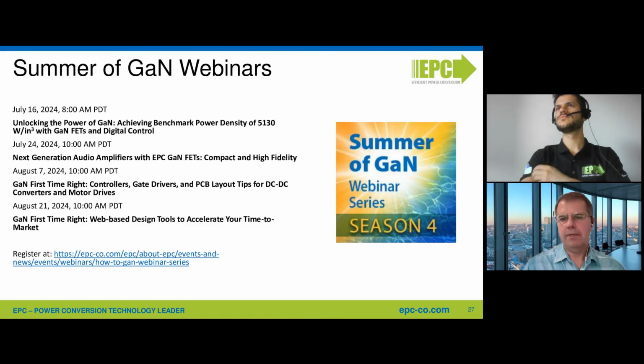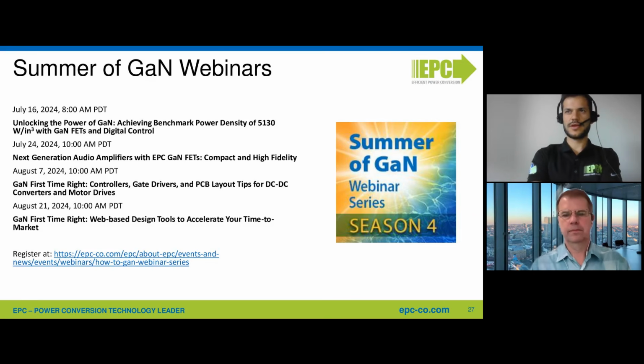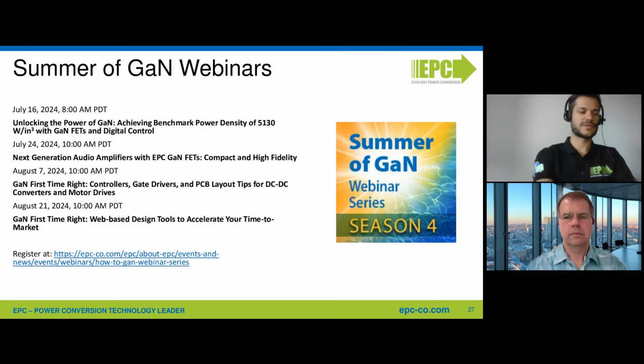Excellent. All right. Now this question might be related a little bit to the first question: how do you optimize the reverse current flow without an additional diode in parallel? There are two ways. The first one is, of course, to reduce the dead time. I didn't point it out clearly earlier, but because of the higher voltage drop in the reverse conduction, having a small dead time helps in reducing the losses due to the reverse conduction.